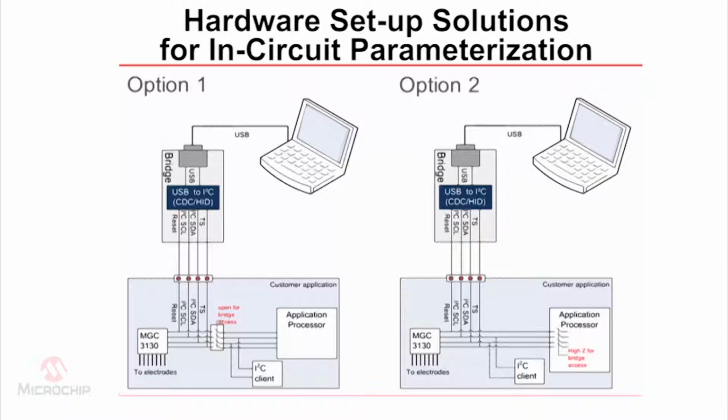In many applications, the I2C interface is used to communicate with the application host processor. Thus, the application host processor needs to be disconnected from the SDA, SCL, TS, and reset lines before connecting the Hillstar I2C to USB bridge. This can be realized in two different ways.